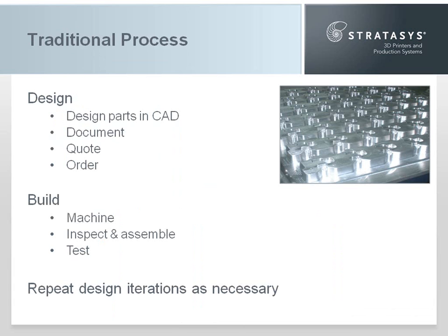Traditionally, jigs and fixtures are machined or fabricated out of either a wood, metal, or plastic material. Like the items that they're used to produce, these tools often go through a design, documentation, and production process. For an elaborate or intricate tool, there may be a prototyping, evaluation, and design iteration cycle to produce one of these jigs or fixtures. On average, the production of a manufacturing tool may take 1 to 4 weeks. This means the process can be slow and expensive, even if designs are kept simple.